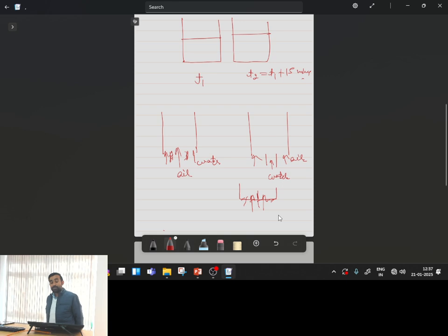Moreover, each of these types has its own benefits. If you are talking about chemical reactions between the two components, or heat and mass transfer between two components, then dissociation of a larger volume into smaller volumes is a good requirement, because then the interfacial area increases. The more the interfacial area, the more the heat and mass transfer, and the faster the reaction between the two reacting species.